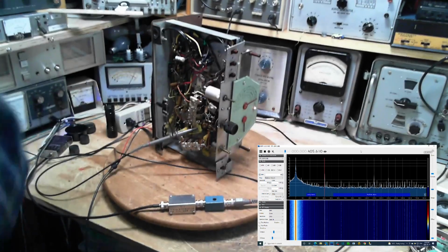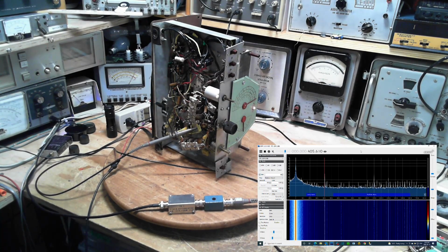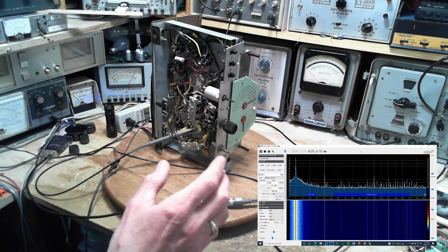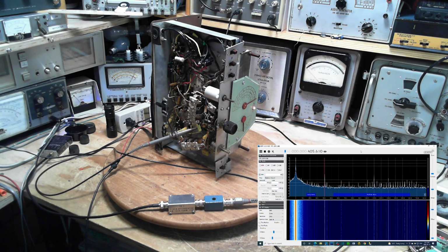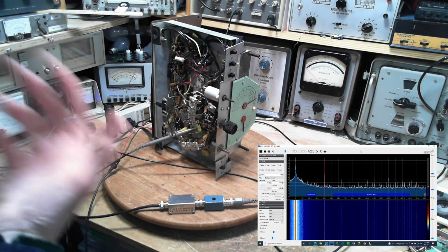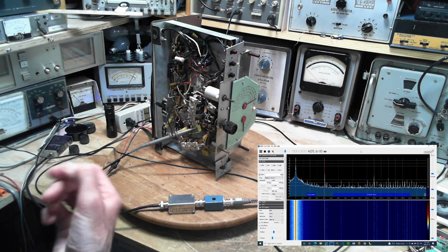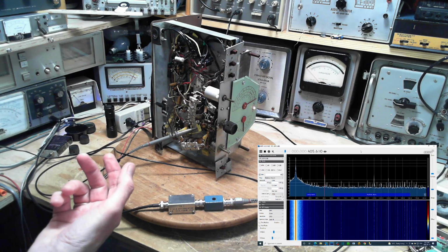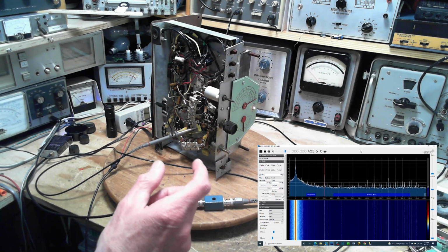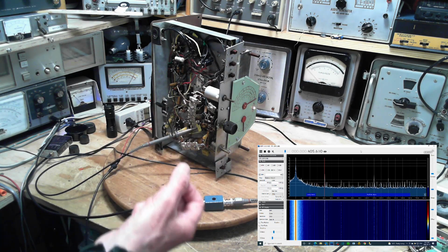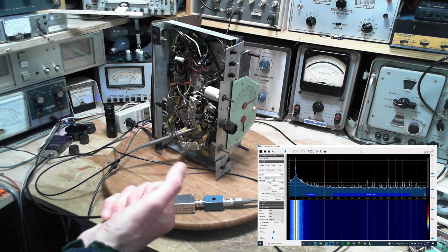405. So this is probably because the apparatus setup I have has detuned the first IF transformer, and its effect is no longer centered on 455. It's now centered on, well, maybe 405. So 405 has become the resonant frequency of the first IF transformer. So anything coming out of the detector, the mixer tube, I hope I'm not mixing too many terms up here, anything coming out of the mixer tube is encountering a resonant circuit not at 455 but at 405. That's probably what's happening.